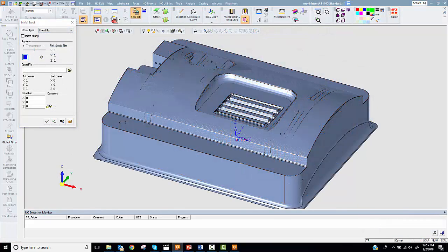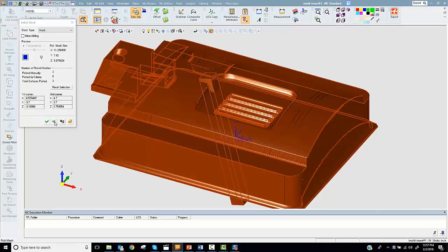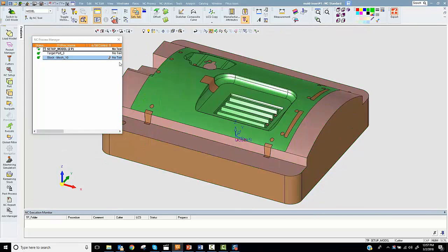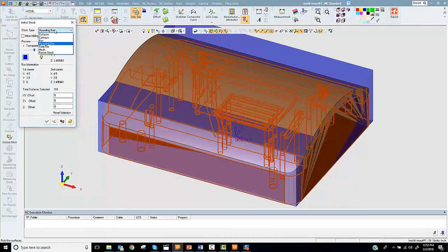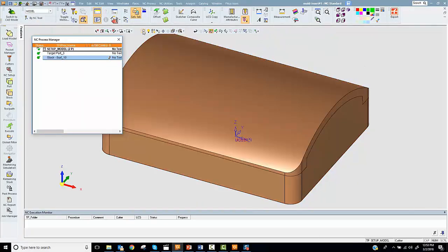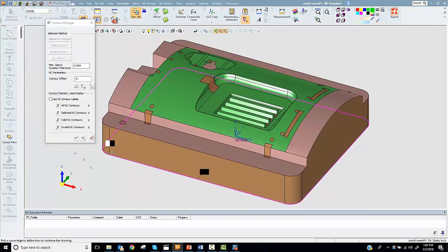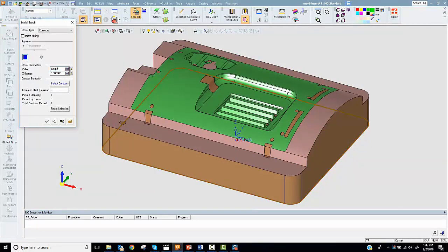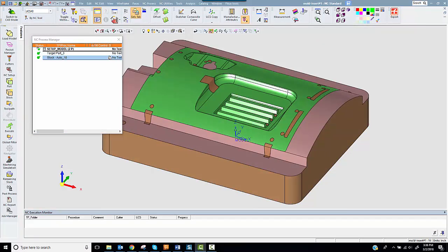Stock may be imported from an STL file, such as a scan or an export from another system. From a mesh or group of meshes imported into the file, like the cam, lifter, and core shown here. From NURB faces, modeled or imported. Or from a 2D contour with heights defined. So I jump back to the original bounding box with some offsets.